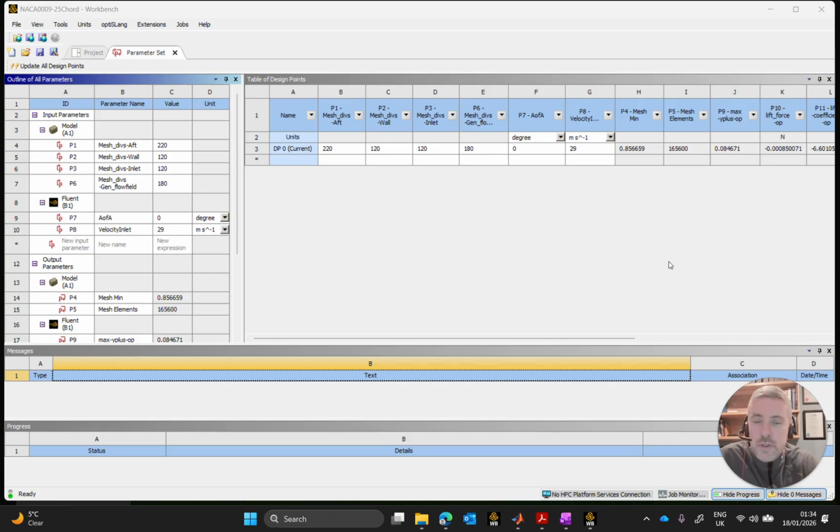Momentary lapse of concentration, but any time that you do set up named expressions or specifically report definitions, and you're going to do a parameterization study or parameter study using a table of design points, which will have subsequent calculations after your initial calculations without accessing the Fluent application, you should definitely save your changes for subsequent calculations.